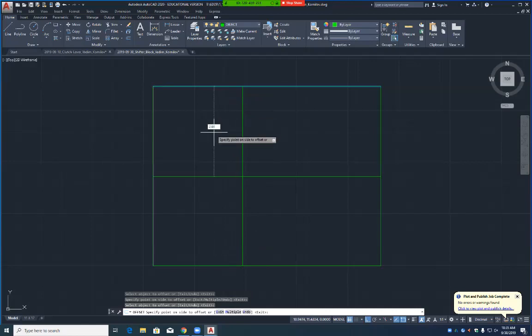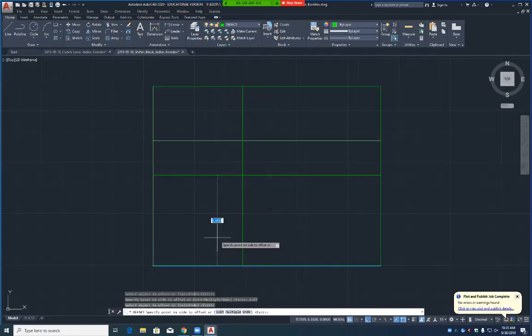Now, don't change the dimensions. You got to follow the drawing. Then we're going to draw a hole here. The diameter of that hole is 1.375, isn't it? So go to circle, center diameter. Come over here to the intersection or midpoint here and go 1.375. Just slow it down a little bit.